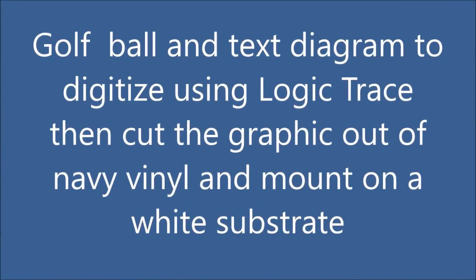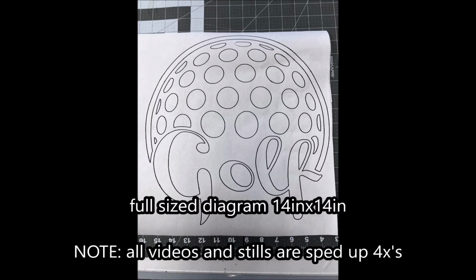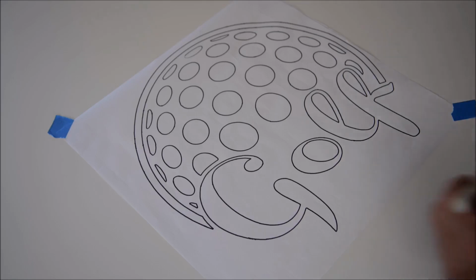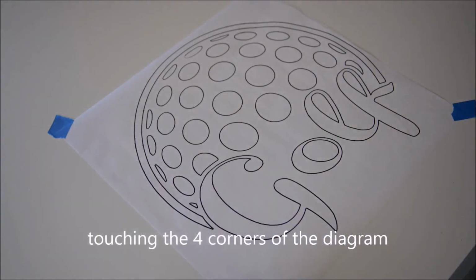I'm going to digitize a 3D looking golf ball with some text. This is the diagram that I'm going to trace out using Logic Trace. First thing I'm going to do in Logic Trace, I'm going to define the four corners by selecting 4 points. Shown here, I'm touching the 4 corners of the diagram, and that will display the size on the program.